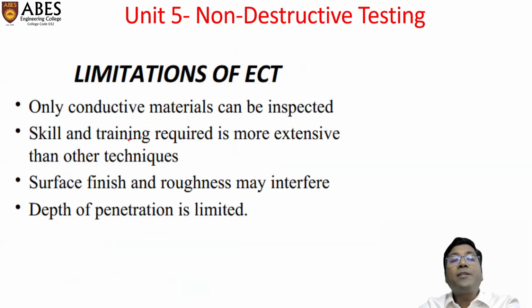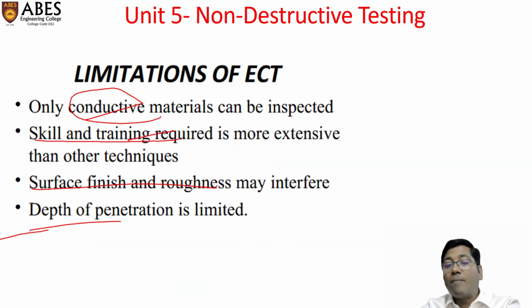But what are the limitations? Only conductive materials can be inspected. Skill and training required is more extensive than other techniques. Surface finish and roughness may interfere with the result, and also depth of penetration is limited.